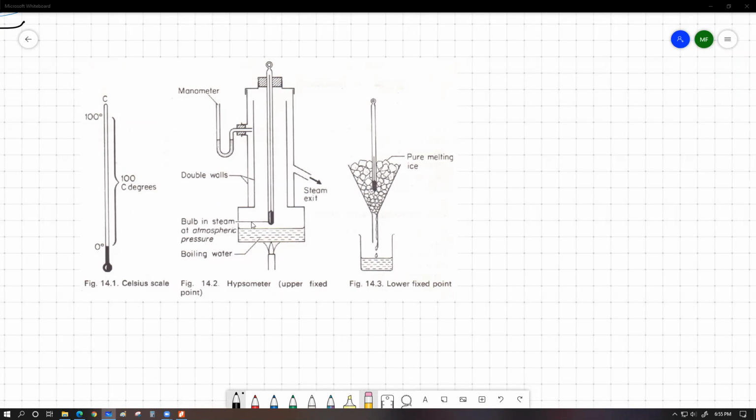The steam will essentially produce over here, and because it is lighter than air, because it is pretty hot, it is simply going to start blowing out. All the steam is going to go to the atmosphere, and practically you can never have the mercury within this thermometer reach 100 degrees Celsius, because the steam would not be present there to raise the temperature of the mercury in the glass. To achieve the 100 degrees Celsius rise of the mercury, we have to trap the steam over here, in contact of the mercury, in contact of the thermometer, so that the mercury can actually reach the temperature of that steam. This is why we need a cover.